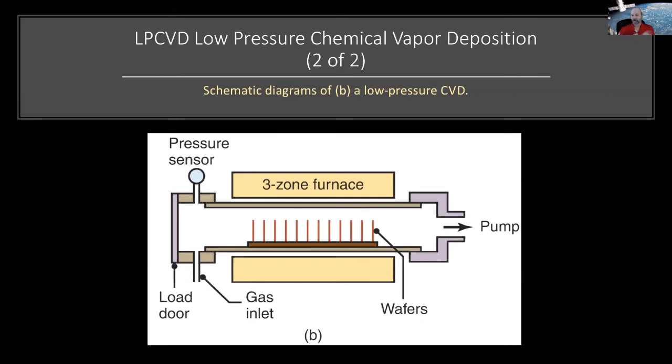The way we deposit polycrystalline silicon is we need a source of silicon, and that's silane gas typically. We flow silane gas in there, and it breaks apart in the heat. The silicon forms on the wafer in small crystals, polycrystalline structures. Actually, we deposit the polycrystalline silicon on top.